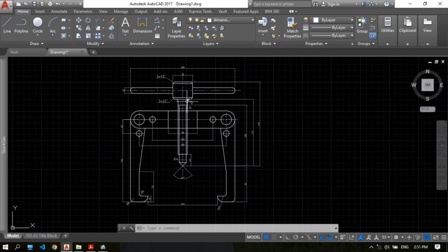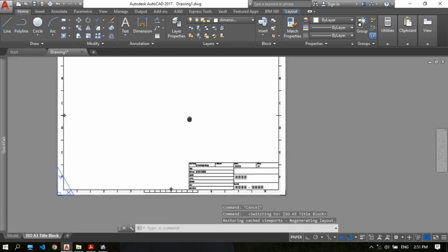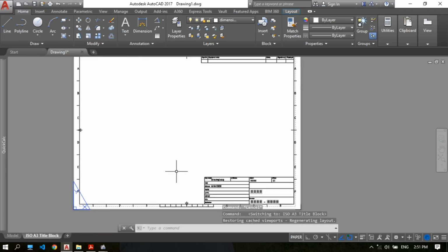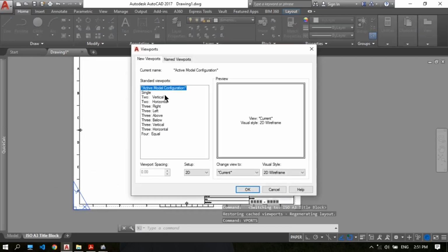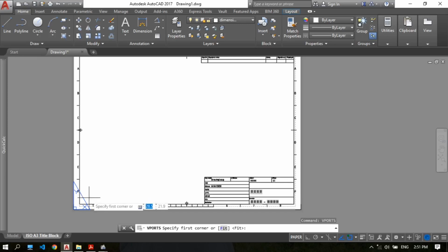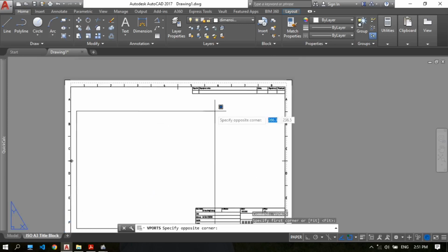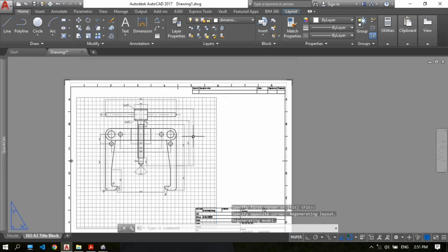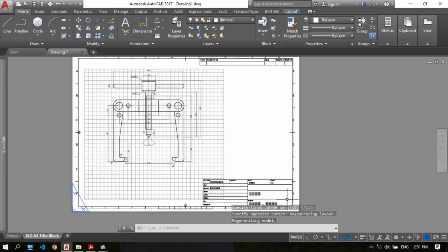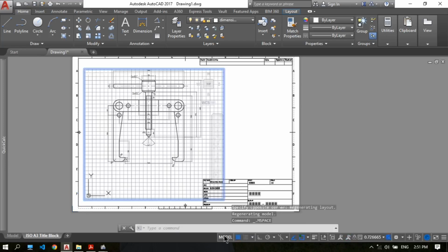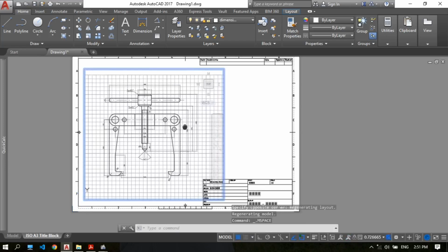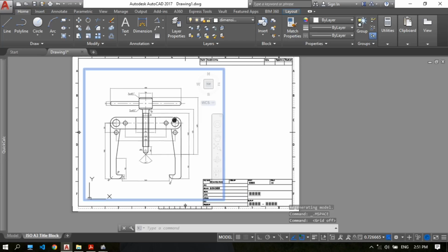If you want to output a PDF of the drawing, you can do it easily in the layout tab here. This is the drawing file here. This is the A3 default viewport here. Edit model configuration, OK, and then click here. Yeah, and then this is the paper. So you can switch to paper here. Display drawing grid off.